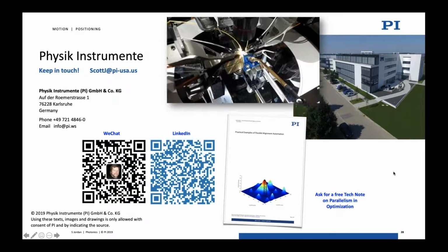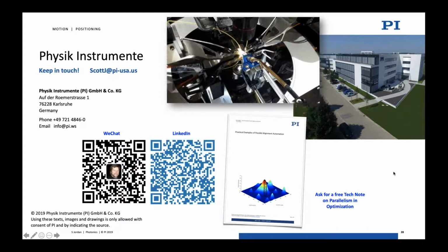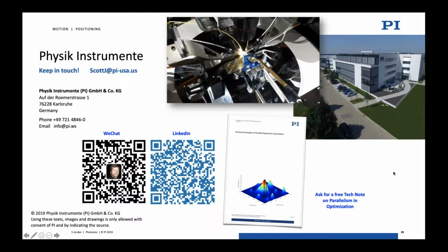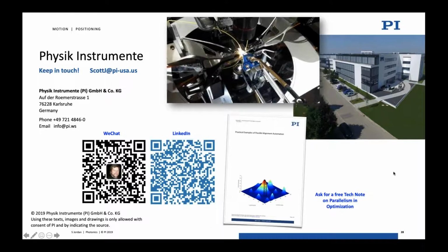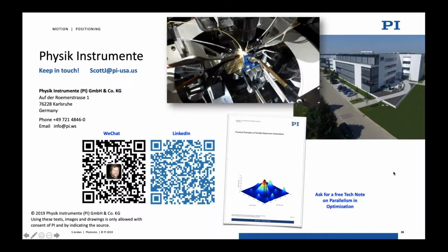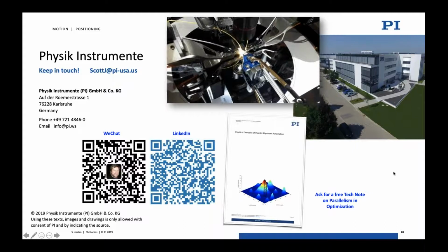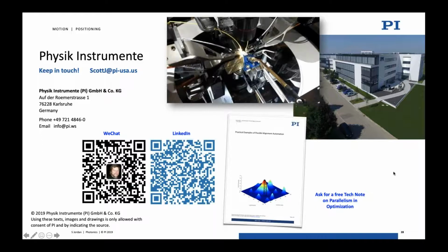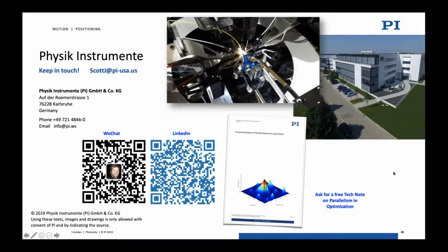Couple of ways of doing that. First, there was one application where we had an output from a polarimeter, an instrument that would measure the polarization vector and the amplitude. And it was a hill-shaped function that when the rotation was correct, the physical rotation of the elements, then the polarimeter would be peaked, and that's what we needed to determine the correct rotational orientation of the devices.